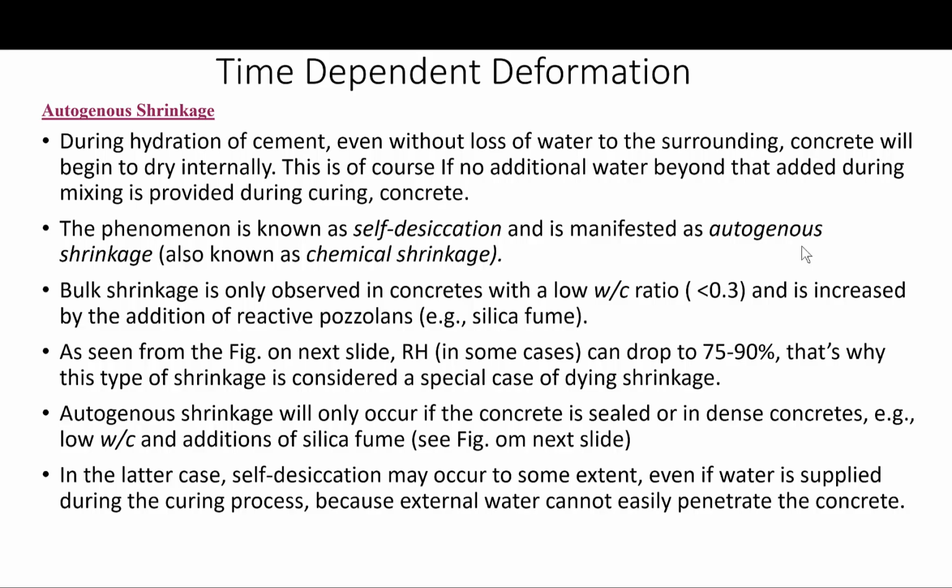Okay, let's look at the other type of shrinkage I mentioned at the beginning of the lecture, which is autogenous shrinkage. If no additional water beyond that added during mixing is provided during curing, concrete will begin to dry internally, even if no moisture is lost to the surroundings, as water is consumed by hydration.